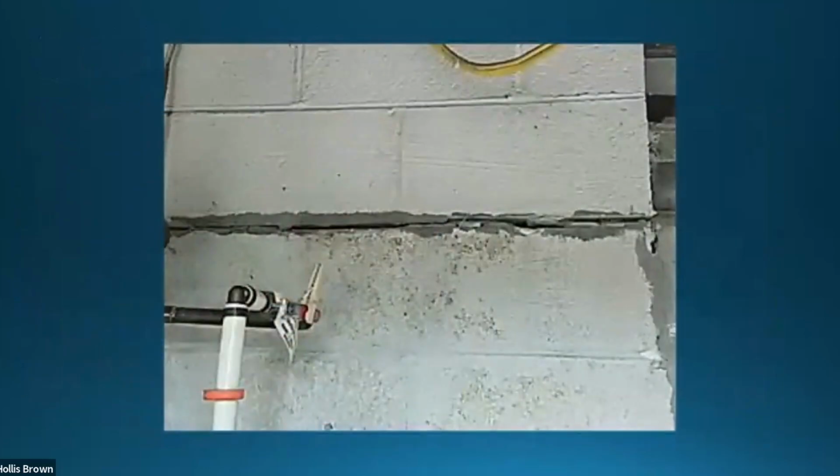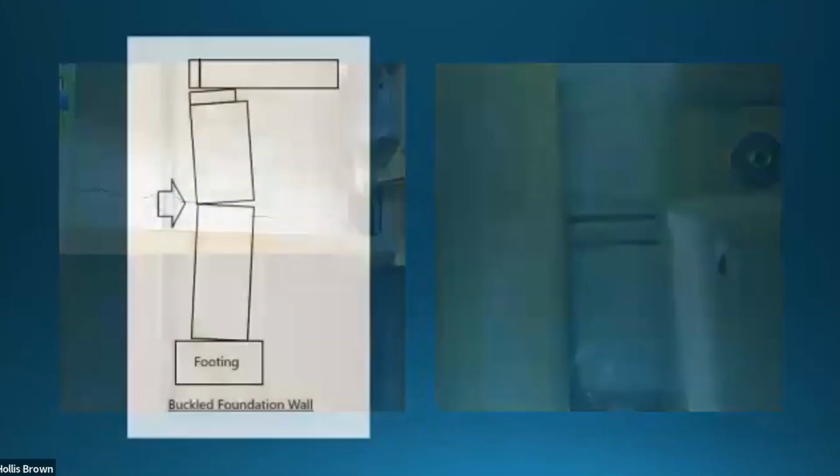So that being said, in my experience, the times that I've seen foundation failures, and I think you'll say, as I say this, yep, you're right, they're usually houses between the late 1940s and 1970s when concrete block foundations took over from the brick foundations. They had hollow cores, no horizontal joint reinforcement, and no steel rebar or concrete. And they failed miserably, and you see it all the time. And that's what these are. This house is probably about 1952, I think, and the walls are coming in pretty good.